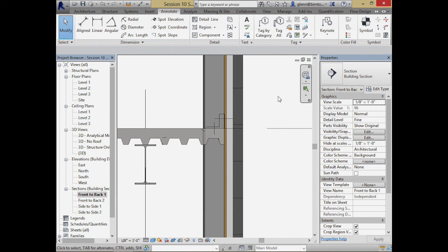So why do they do that? That facade system just gives you an awful lot of independence. They didn't have to engineer the stone and everything inside of it to carry the loads. It's just really more a facade. In fact, there are some really interesting places where they're joining them together, where you can see the stone come together. See if you can spot the joints, where it looks like brick, like the stone is interlocked with the other, and you can spot where the panels actually came together, and there's just an expansion compound in there that gives it that appearance, but it isn't like a big solid stacked stone building.